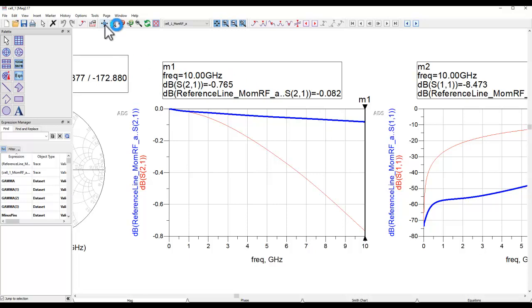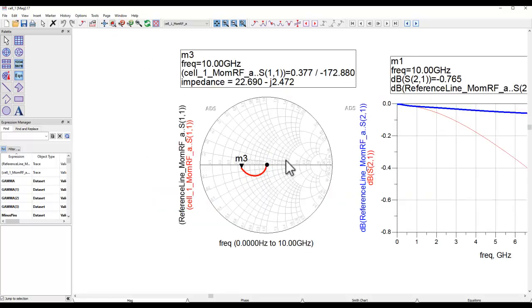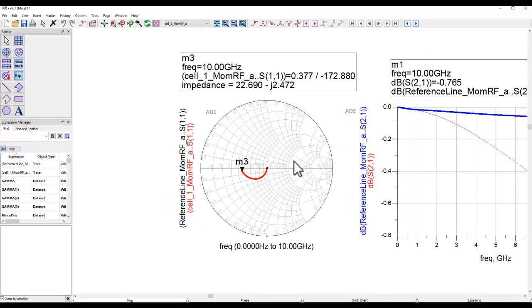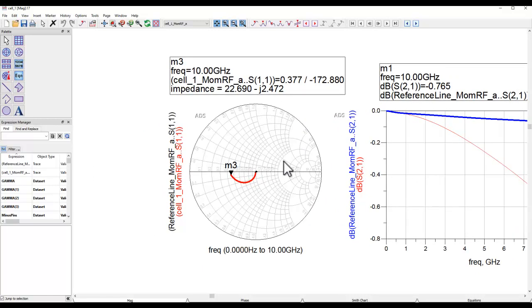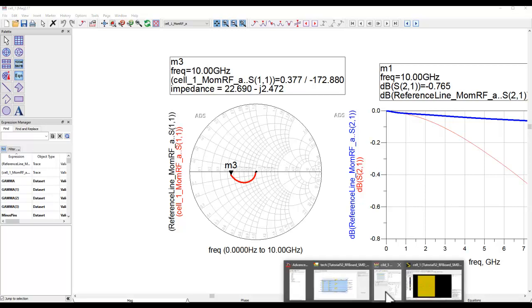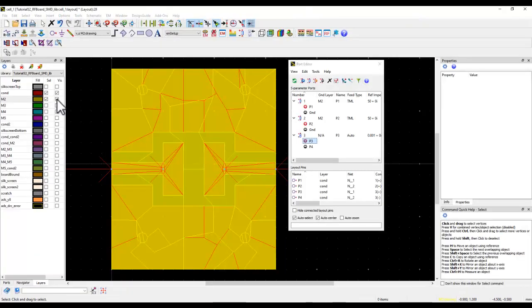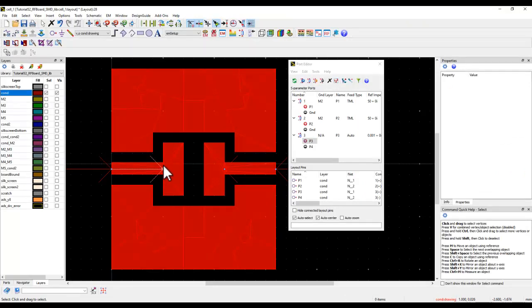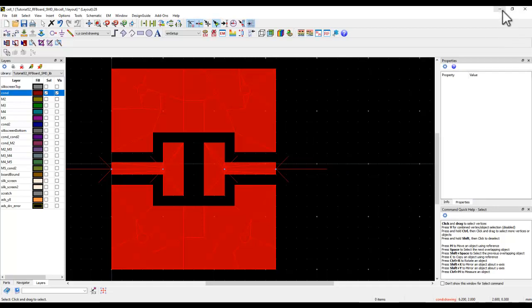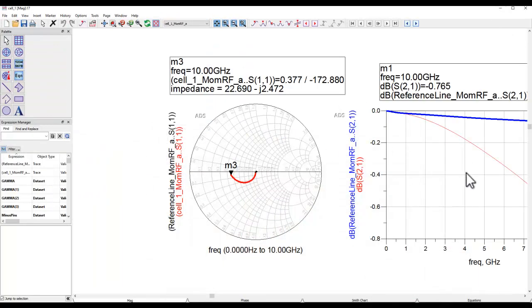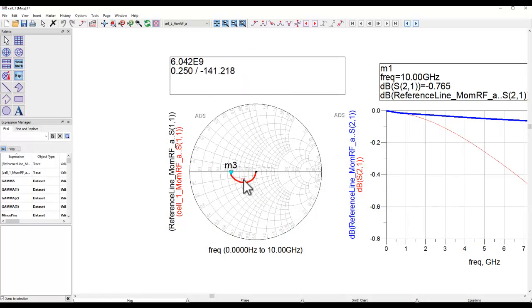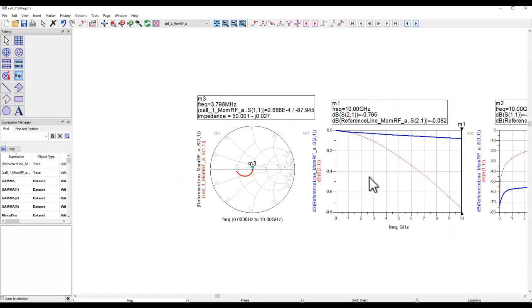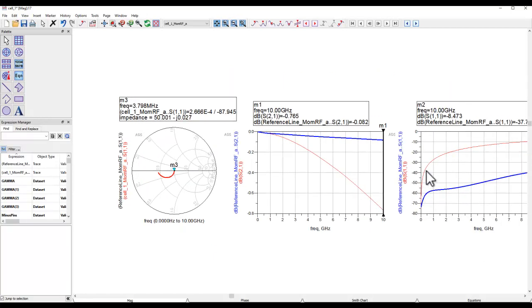Now, why is that happening? Well, we all understand by theory that a wide transmission line is going to be a low impedance line, obviously. So your 50 ohm line is getting meshed with a low impedance line, so you will have reflection at that point, and that's where the energy is getting lost. Hence, you have a higher insertion loss. Also in the Smith chart, as you can see, at the lower frequency your line is close to 50 ohm, and that's what you also see in the return loss. So at the lower end of the frequency, your return loss is pretty good.